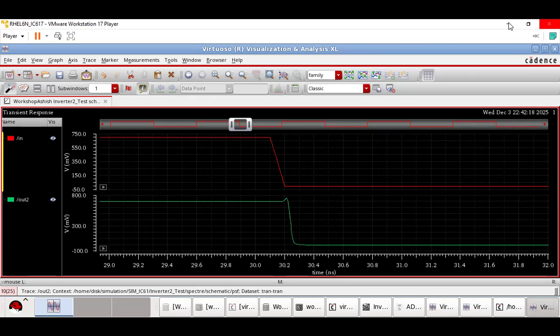See, if you want to put one value for your circuit, there are multiple cases. One is that you want to show the rising case or falling case separately. If you have to give one value out of those, then you should give the higher value, because the rest of your circuit will be dependent on the maximum delay. Okay, sir. You should always quote the maximum of both.